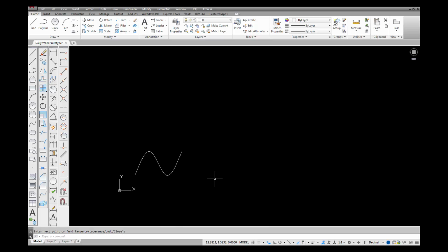If you are using a previous version of AutoCAD, version 2011 or older, you actually hit your enter key a few times before it'll exit out of the command. I believe you have to enter it 3 times and then it'll finally exit. But that is for earlier versions. More recent versions, post 2011, you'll be able to just hit enter once and it exits out of the command.